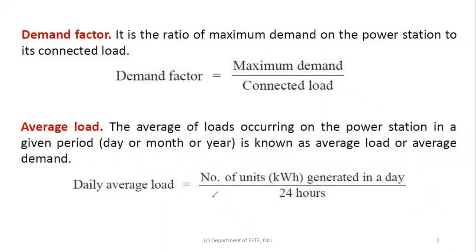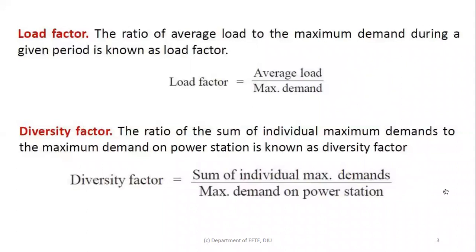You get the total hours of 8,760. This is the total hours in a year, in an annum. So this is how we can get the daily average load, the monthly average load, or the yearly average load. The next is load factor.